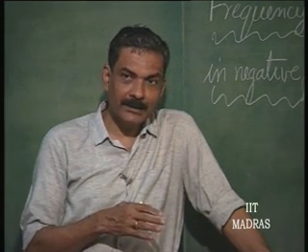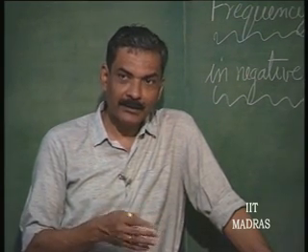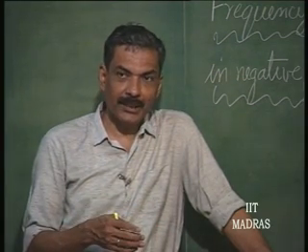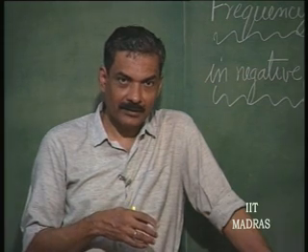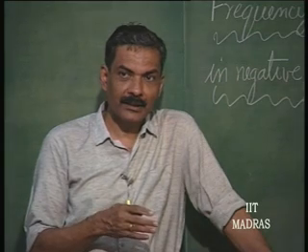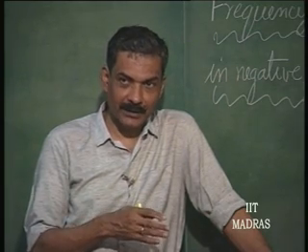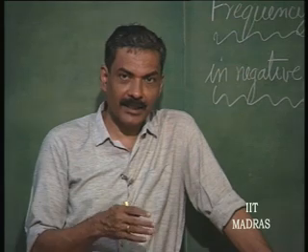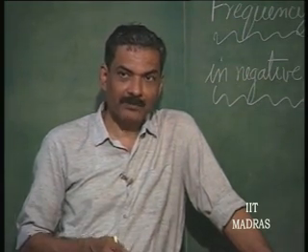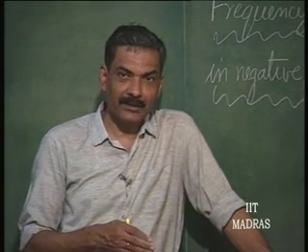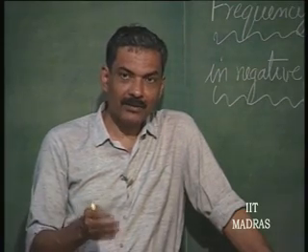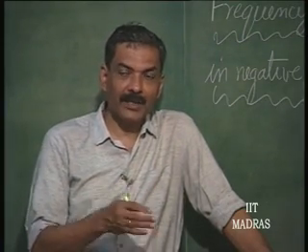Further, we discussed the aspect of making a sinusoidal oscillator by simulating a second order differential equation, or making the poles get located on the imaginary axis. In all our filter functions, the poles must necessarily get located on the left half of the S plane. In the case of an oscillator, it can lie on the j omega axis, or preferably, in order to make it go into build up of oscillation, we purposely locate it on the right half of the S plane and then bring it over to the imaginary axis slowly at the required amplitude of oscillation.